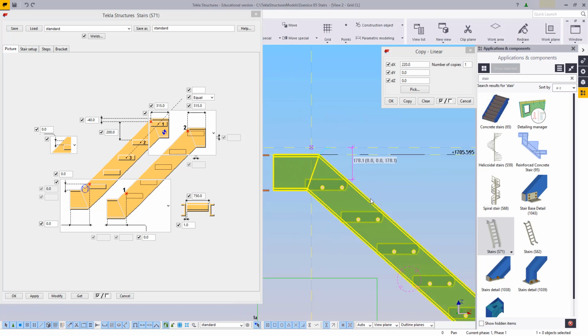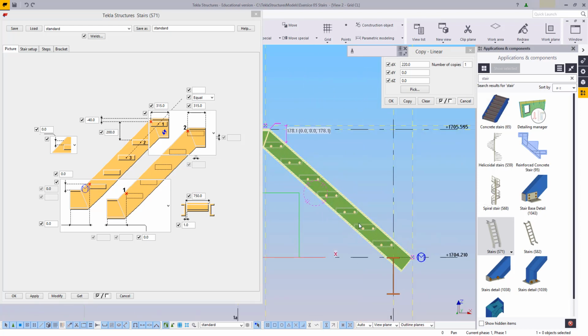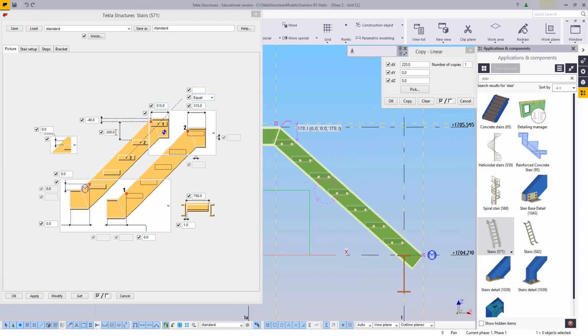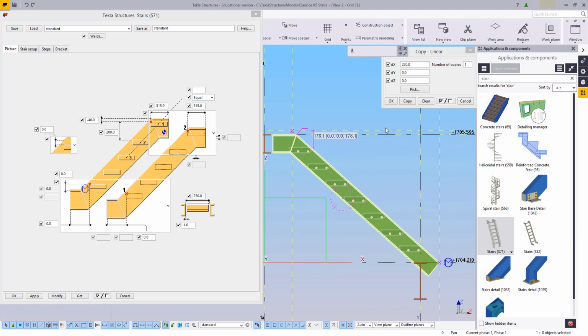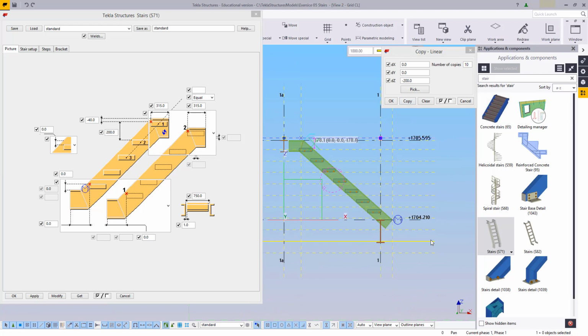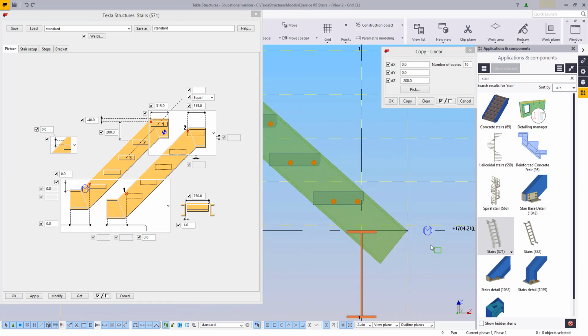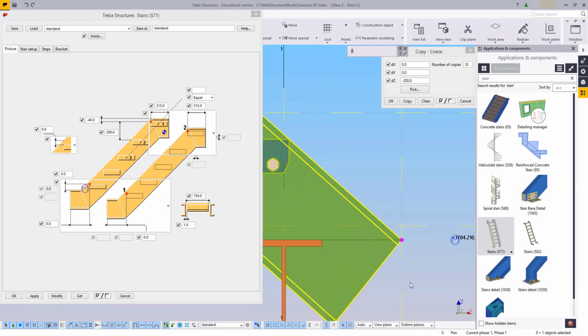Now the reason for this can be quite easy to figure out. It just means that I've divided it equally, and the distance it's currently cannot be divided into 200 equally. So what I'm going to do is take the top line and copy it linear down, minus 200, and I'm going to have 10 of these. Doesn't really matter, I'm not going to use the extras at the bottom, but it's a lot faster than trying to figure out how many there are.